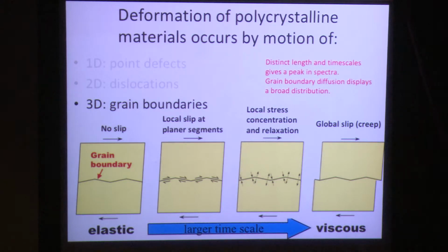And it turns out that the response we get is a very distributed, wide distribution of time scale in frequency space. And so the thought long ago was that, well, you must have samples that have a distribution of grain sizes, and so that's giving you this broad distribution. But then experimentalists, a couple decades ago, were really careful to try to isolate this grain boundary sliding process and mechanism. They very carefully got very uniform grain size, say 3 micron, and they removed all the extra impurities.